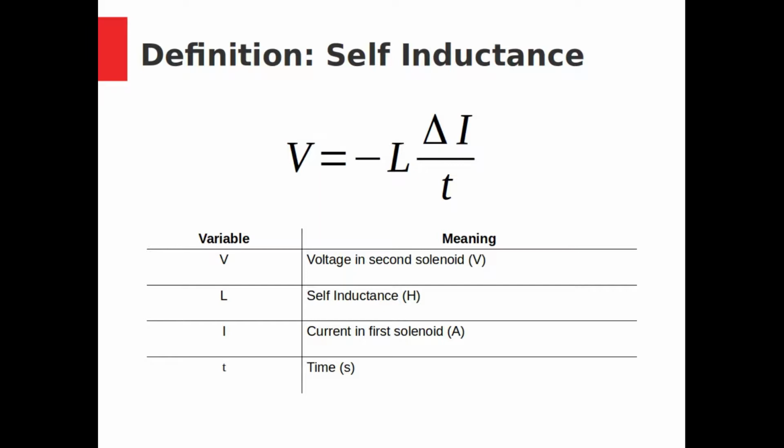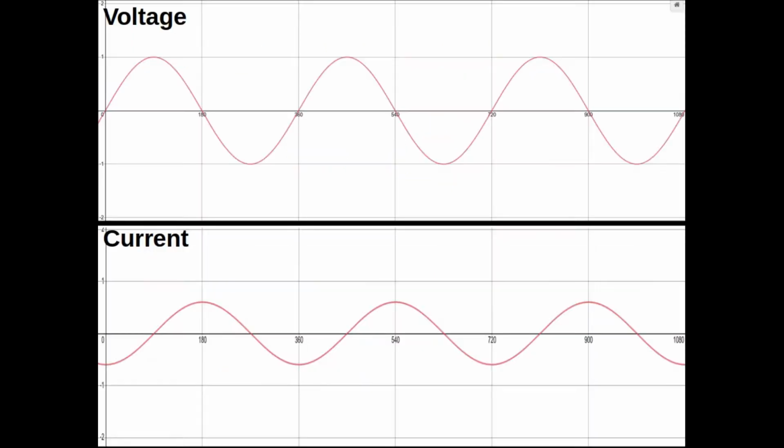More specifically, if the voltage is falling through zero, the current is at its maximum. And if the voltage is rising through zero, the current is at its minimum. Long story short, once the system stabilizes, we get a pattern like this. The current always reaches its peak or trough when the voltage is zero, and vice versa. Also, the current always reaches its peak after the voltage does. So we would say the two waves are 90 degrees out of phase with voltage leading and current lagging.